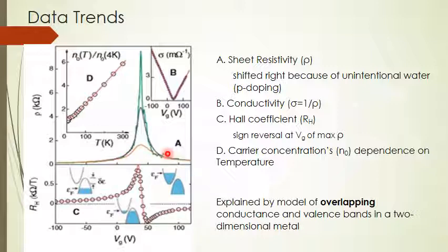Researchers believe that the intrinsic few-layer graphene is a mixed carrier semiconductor because water exposure led to p-doping, yet ammonia doping led to n-doping. Carrier mobility is determined from field effect, and magnetoresistivity ranged from 300 to 10,000 centimeters squared per volts times seconds.